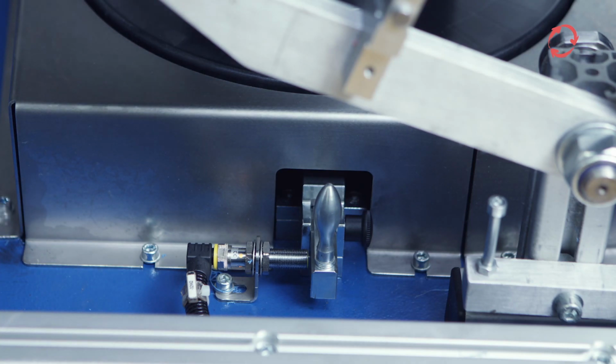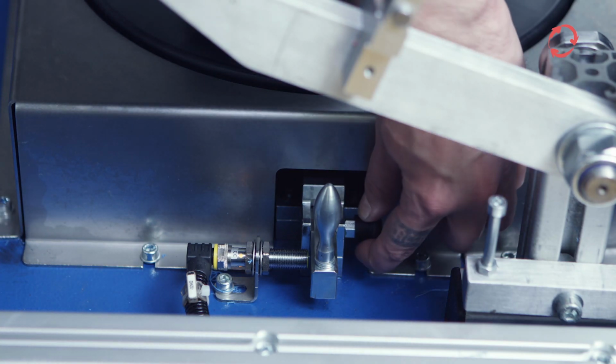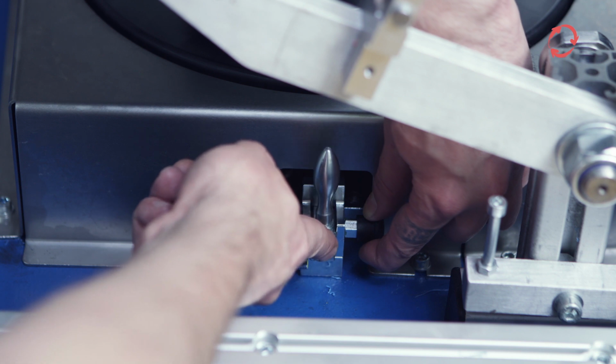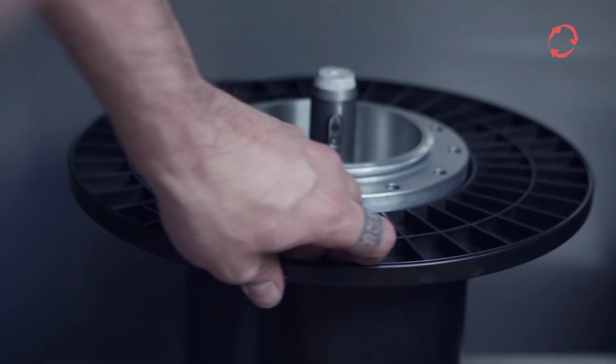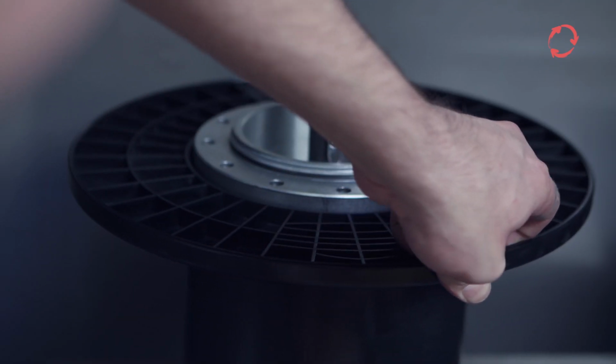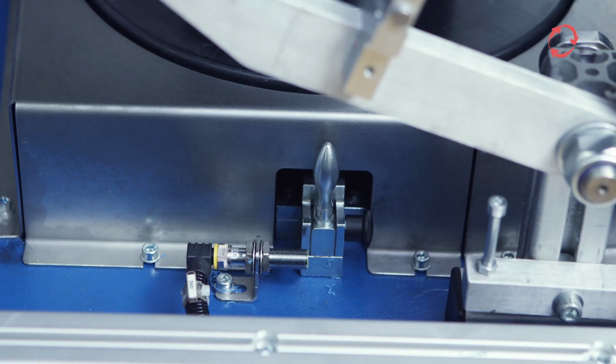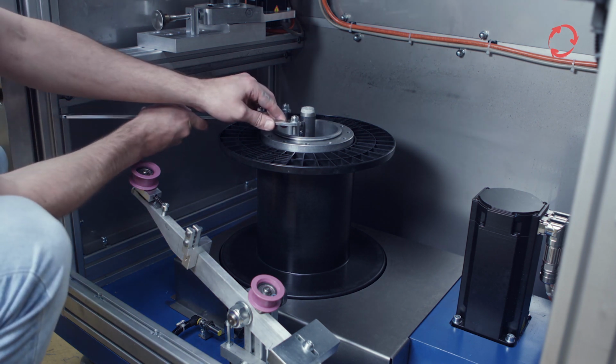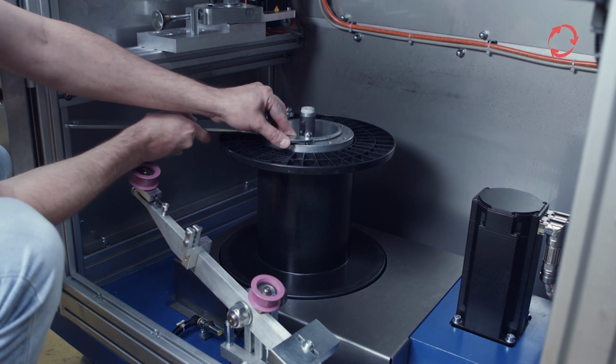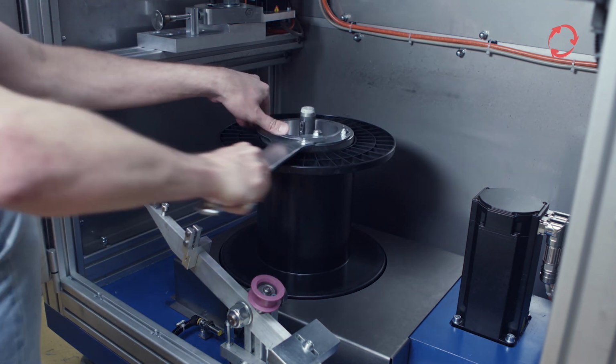Lock the spindle and coil by pulling out the black safety mandrel and pushing in the slider. Turn the coil until it clicks into place. Now the small LED has gone out and the coil is locked. Open the clamping disc with the hook wrench and remove the coil.